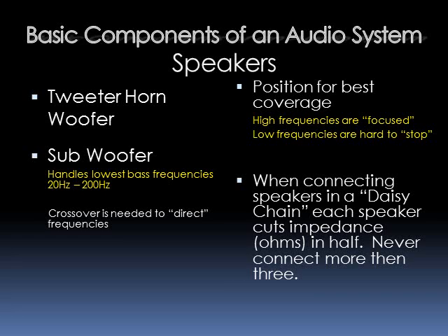This is kind of an important side note, but you should really know the basics. When you're connecting speakers in a daisy chain, usually monitors across the front of a stage or something to that effect, each time that you connect a speaker, it cuts the impedance in half. Again, I said I was going to keep this simple, so just think of it as your speakers are going to be set up at 8 ohms. You cut it in half, that's 4. Cut it in half when you add a third speaker, that's 2 ohms.